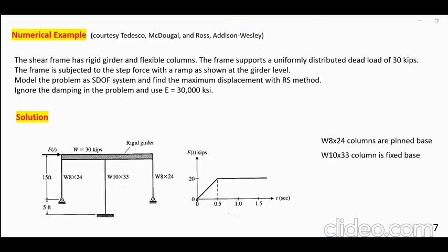The load varies like that. So after half a second, the load reaches a value of 20,000 PSI and stays like that. So this is how the load is applied, and we want to find out the maximum deflection under this. Now, notice that the maximum deflection depends on how fast this load was applied.